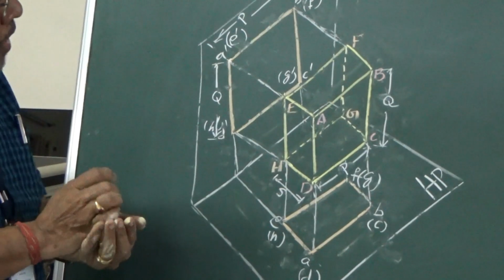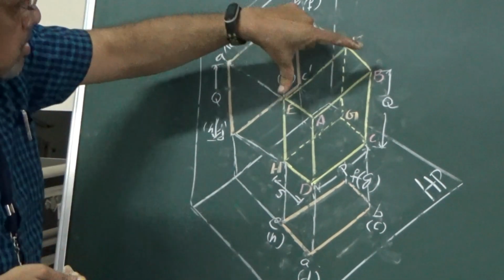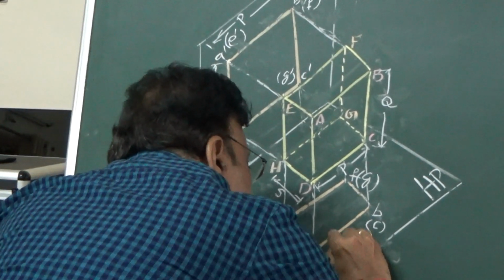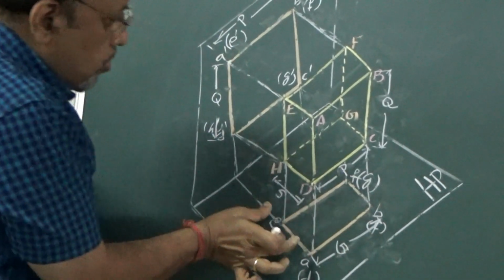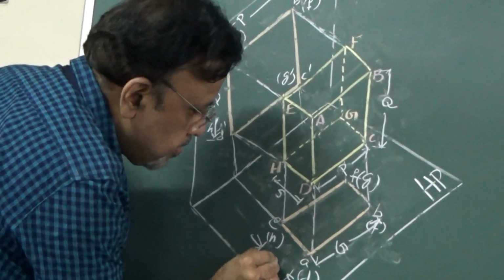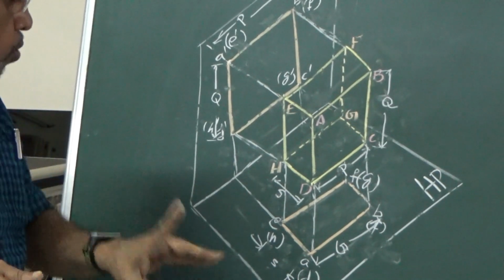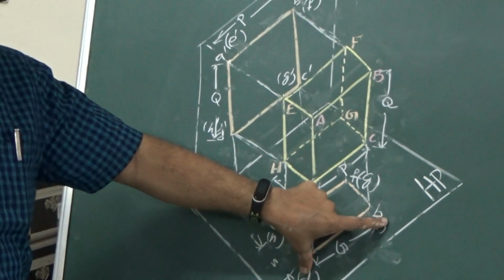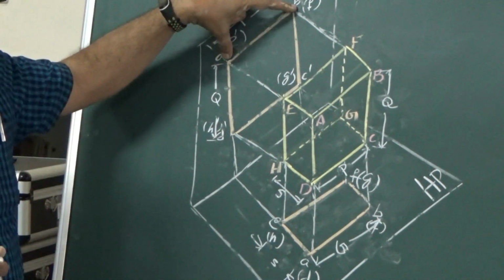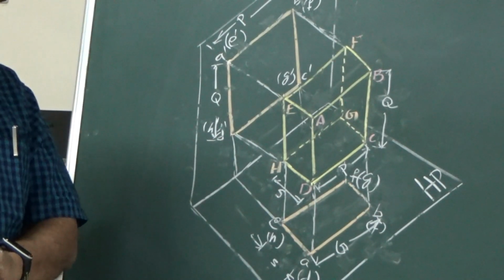Okay, anyway, now tell me, if you look from the top, what are the dimensions I can see? As you can see, I can see this G, so I will represent this as G. Then, what about this? I can see this, yes. Now, we can see that in the top view, I can see only thickness and width, whereas in the front view, I see only height and width. But in combination, I can visualize a particular object.